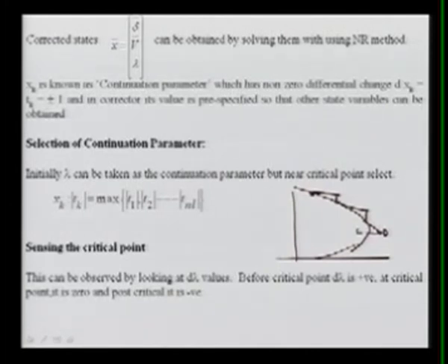So what you have to do, instead, you can estimate the load. Here what we did, we estimated the load, we just moved along the tangent vector, and at that load we got the solution, and then point E, or you can say point B. From B we took one tangent and moved to D, but this point D is out of the solution, meaning unsolvable.